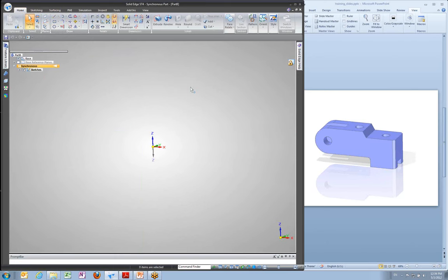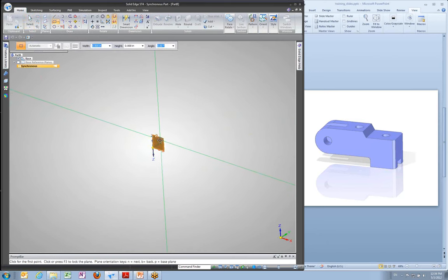I'm going to go to the rectangle by center, and I'm just going to mouse around until I get that plane highlighted between the Z and the X. You might notice if you get too close in there, you might get other planes. We really want this one right here. That's kind of our front plane, and I'll just hit F3 to lock. And then I'm going to hit the sketch view, which is also Control H, and that'll bring me looking straight on this.